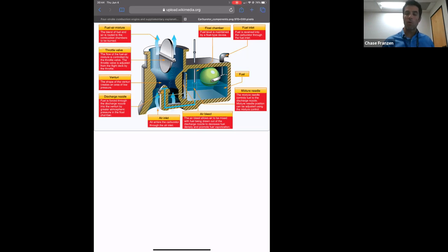The fuel is stored in the wings. You've got a high wing aircraft, so each wing stores 21.5 gallons, so 43 gallons total. You've got a 4-position fuel selector on the floor of the airplane. You can either go left, right, off, or both tanks.